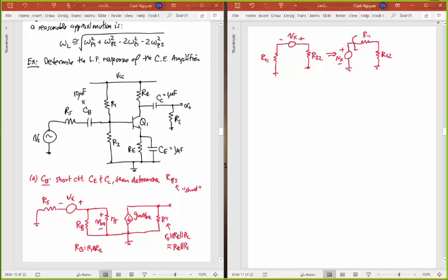And so if I look in this direction from that test source, I can try to measure that test current there, but really no need, because I can see right there that total resistance seen in that direction is just R11 plus R22. So just right off the bat, by inspection, if I see a voltage source like I have on the left between two resistors that are each going to ground, I can just add those two resistors together to get that driving point resistance. So in this case, RBS is going to be Vx over Ix,